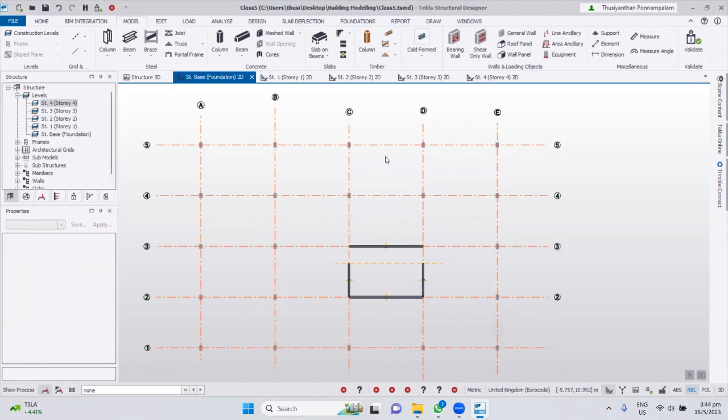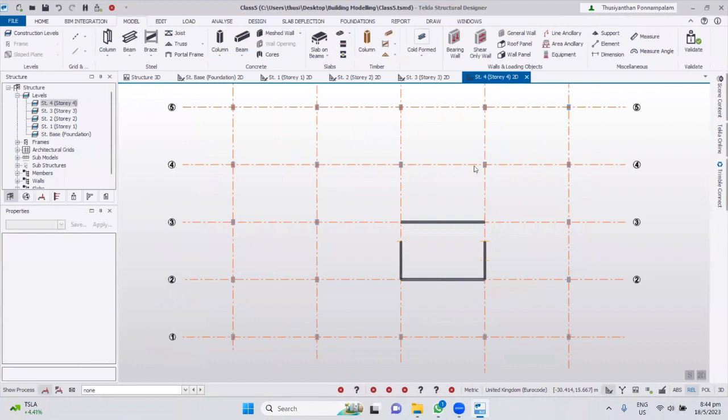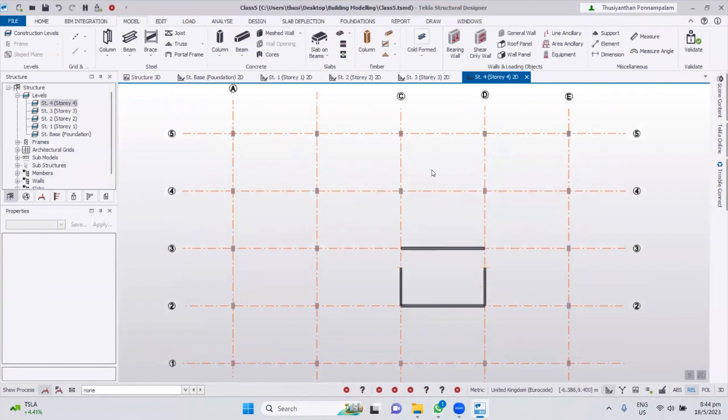Right. So I believe most of you know about the flat slab, right? Normally in the flat slab, we provide the column cap or drop panel, right? So there are no beams. Flat slab means slab with the drop panel. If we go without drop panel, that is called a flat plate. But if you want a flat plate, you want a very thick slab. So I am going to cover the flat slab first. Flat plate is very easy. Actually, flat slab is the more difficult thing. So I cover the flat slab first, right?